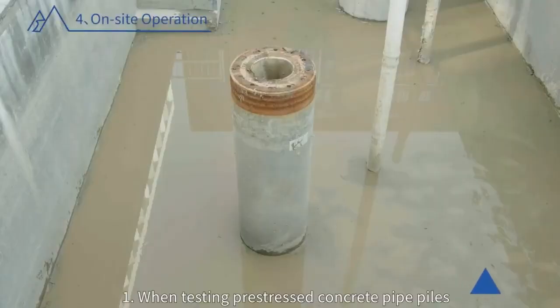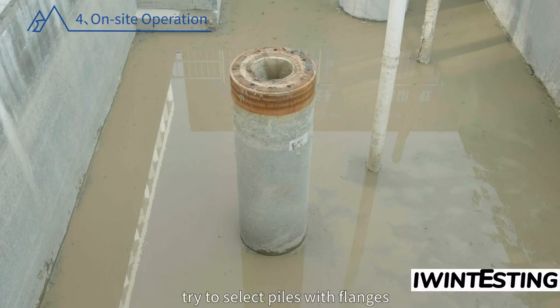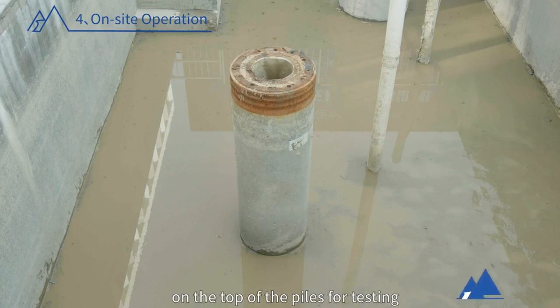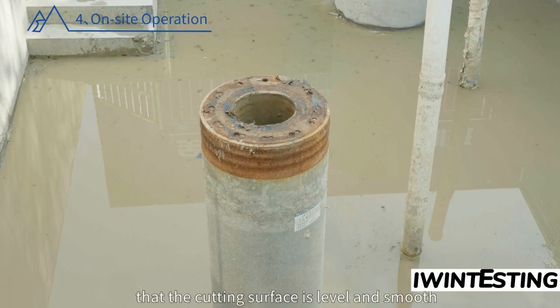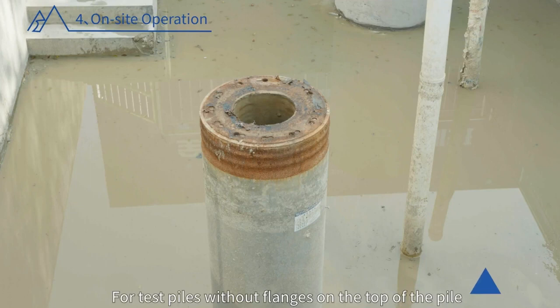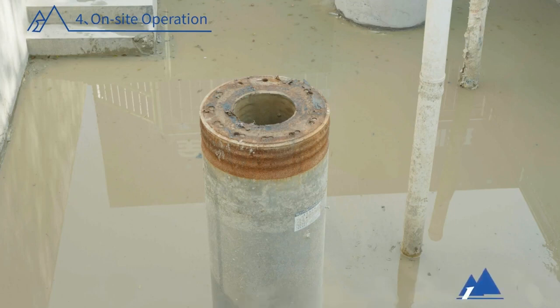When testing pre-stressed concrete pipe piles, if conditions permit, try to select piles with flanges on the top of the piles for testing. If the pile head is damaged, the damaged section can be cut off, but make sure that the cutting surface is level and smooth. For test piles without flanges on the top of the pile, the test can be carried out only after the top of the pile is chiseled.